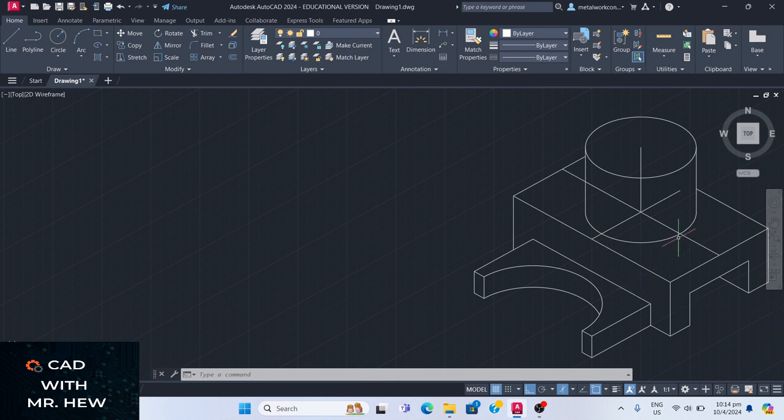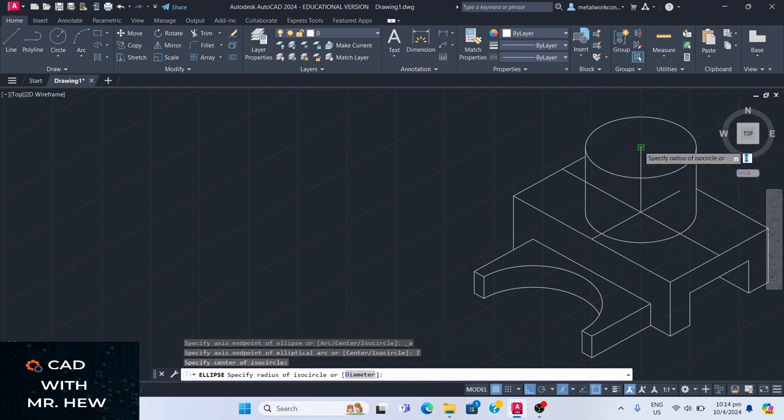All right. So what I'm gonna do, I'm gonna put these lines on the center line. Right? And in a little while you see the reason why I did that. All right, next thing I'm gonna do, I'm gonna draw the circle at the top, right? So we go click this, click ISO circle, specify the center, good. Then the diameter, that is what it is asking for. So these in the square bracket, so it's asking for that.